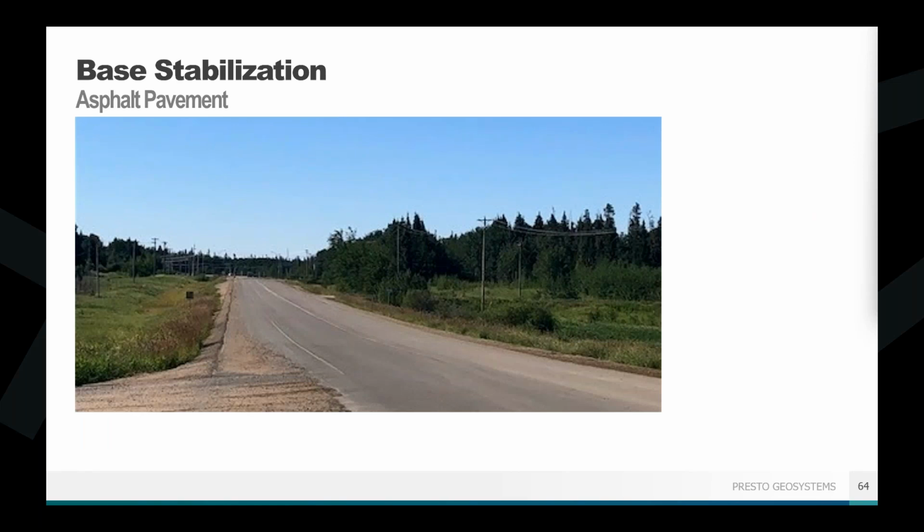It's significantly reduced maintenance, frost heaves, and rutting of the roadway, all because the GEOWEB system mitigates that differential settlement and provides that mechanically stabilized base layer with that really improved stiffness. And so now this roadway is going to perform really well for decades. And we're doing this sort of thing all across Canada and the US. We're doing hundreds of kilometers, hundreds of miles of roadway like this every year.